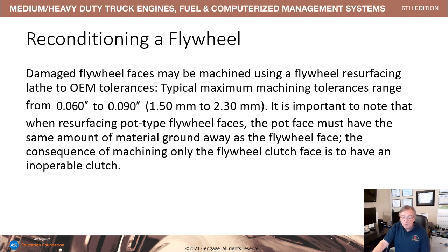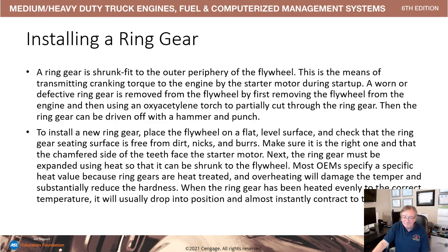Recondition the flywheel. Flywheels are generally surfaced in a specialty shop today. Some shops have the ability to do the clutch face with a wet grinding process in a fixture. I've seen shops do that, and it's a relatively simple procedure, and it surfaces the flywheel so that the clutch will have a good life.